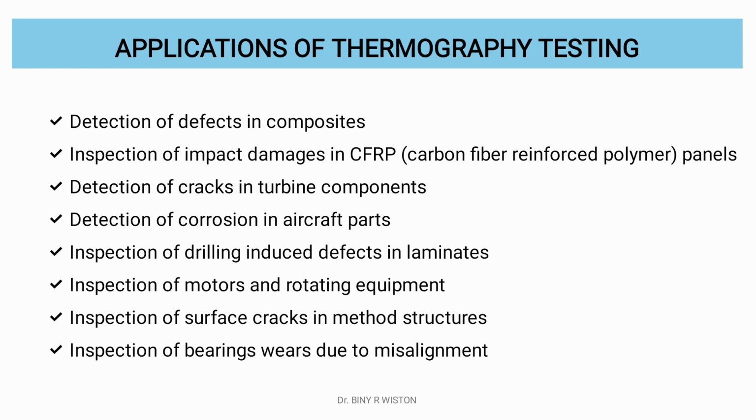The various applications of thermography testing include detection of defects in composites, inspection of impact damages in CFRP, detection of cracks in turbine components, detection of corrosion in aircraft parts, inspection of drilling induced defects in laminates, inspection of motors and rotating equipment, inspection of surface cracks in metal structures, inspection of bearing wear due to misalignment.